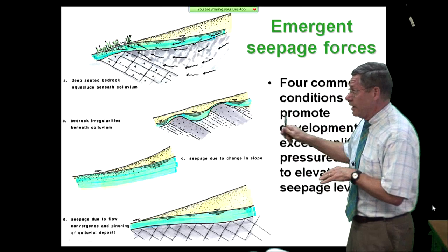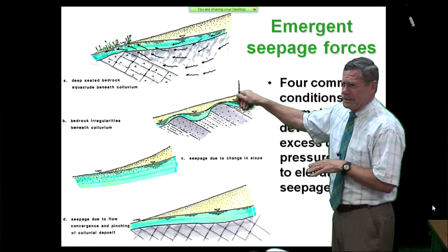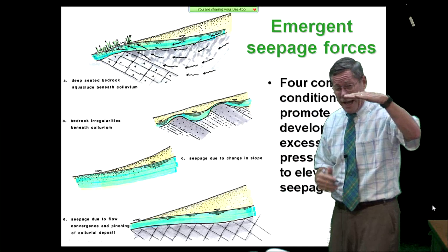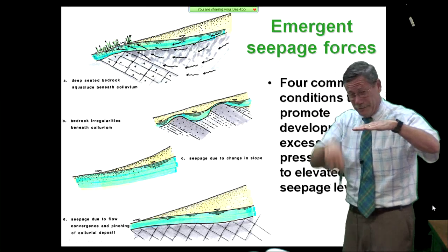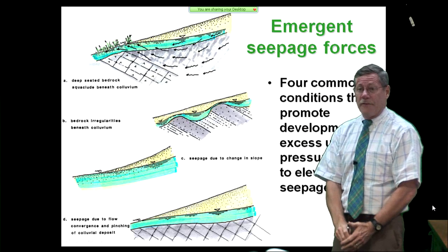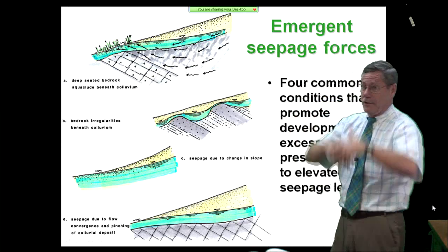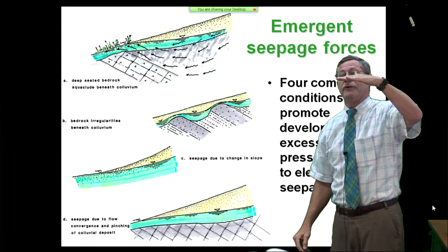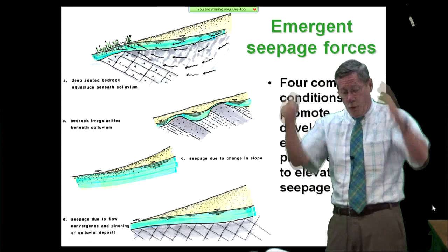And how long do these pore pressures last? A couple minutes, a couple hours. You know, I had one in Hawaii where I had an active slide, pure clay. I drilled into it and lifted everything out of the hole. Lifted our drill rod out of the hole, everything, and we measured 66 inches coming up right here, right in my eyeball level. Water just pouring out.